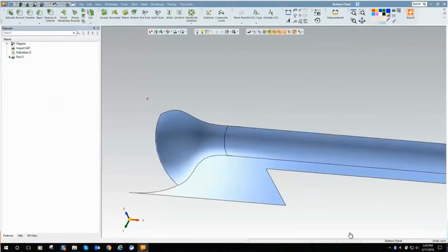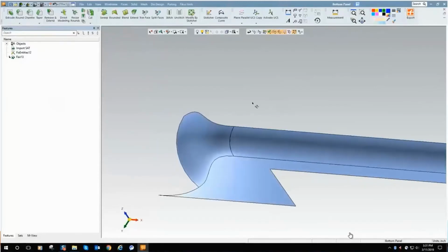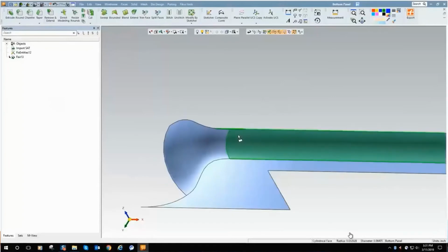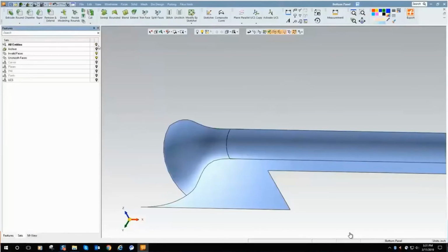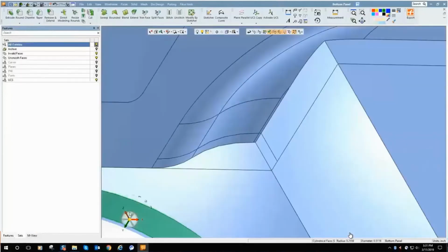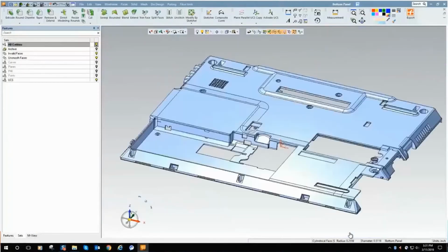As an example, I'll use a function called fair on a surface that looks like it suffered some sort of data translation issue. Fair only took a second to run and relieve some of the stresses that exist in the data. It can definitely help, and you see this surface looks a lot better already. Maybe good enough, or you might decide if it still needs some border work to be perfect.